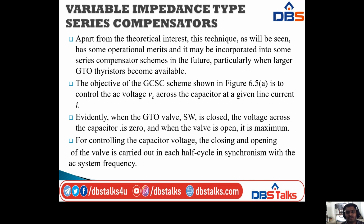The objective of the GCSC scheme, shown in the previous diagram, is to control the AC voltage VC across the capacitor at a given line current I. Evidently, when the GTO valve, that is the switch, is closed, the voltage across the capacitor is 0, that is VC is 0.